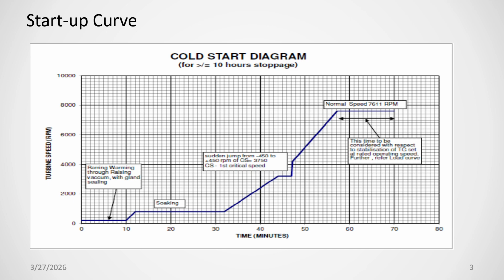Before, after doing a major overhauling, we have to start the turbine to see whether the major overhauling done is okay or not. But during the starting, we have to take all these parameters. We have to be very careful, because the turbine has a starting curve and there are a lot of critical speeds also. So during starting, we have to be very careful.